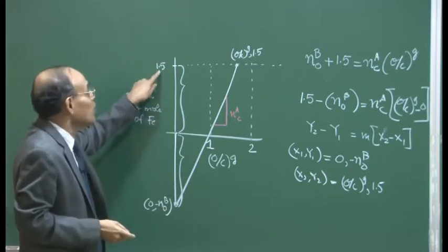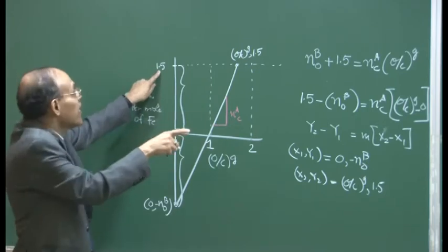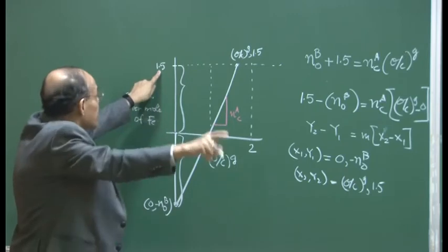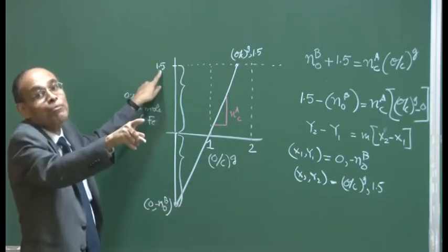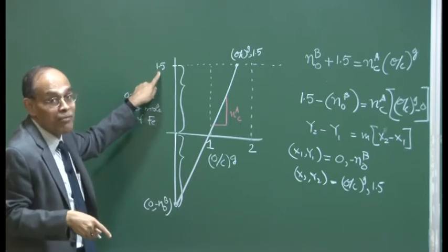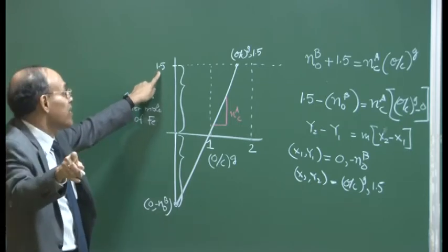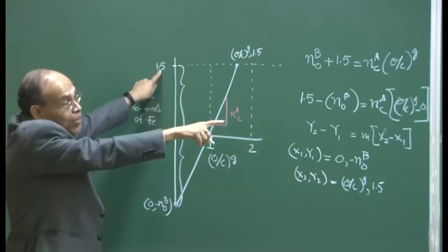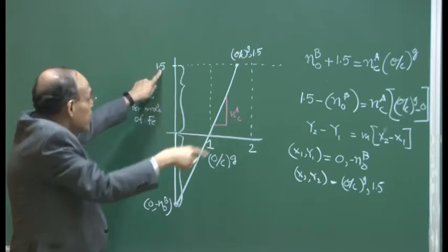And this value of 1.5, as I have indicated, will change depending on what kind of ore you are using, what kind of iron bearing material mix you are using, or what kind of impurities are there. For the idealized case it is 1.5, but when you have a non-ideal case, do not consider this point to be 1.5; it is to be calculated just like the way I have shown it on the extreme right side of the board.